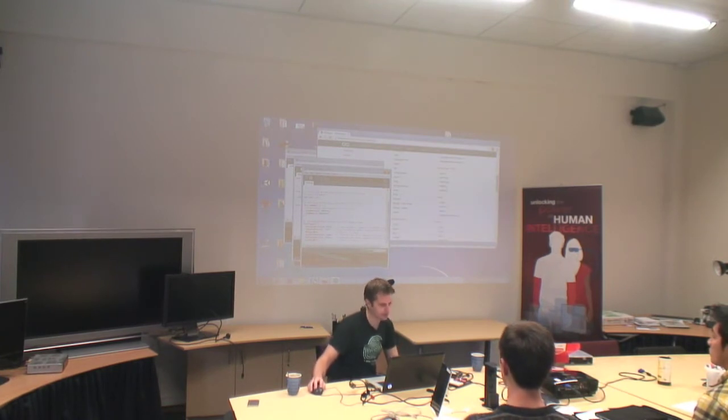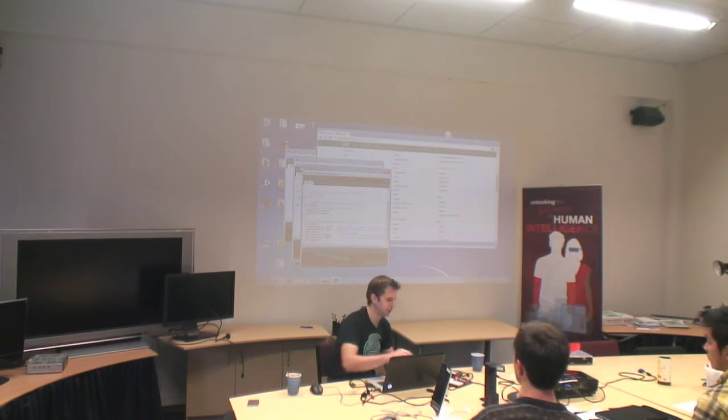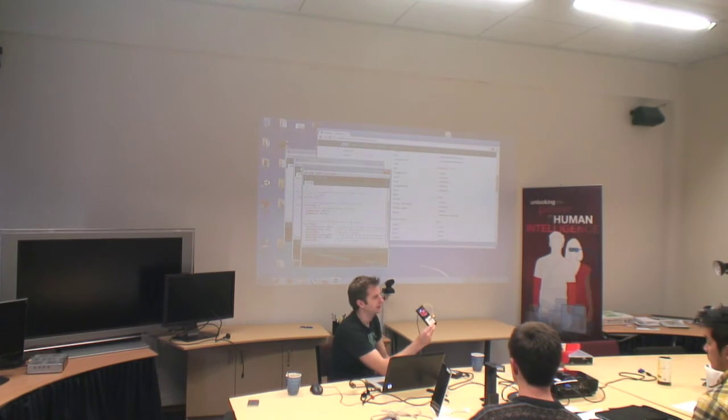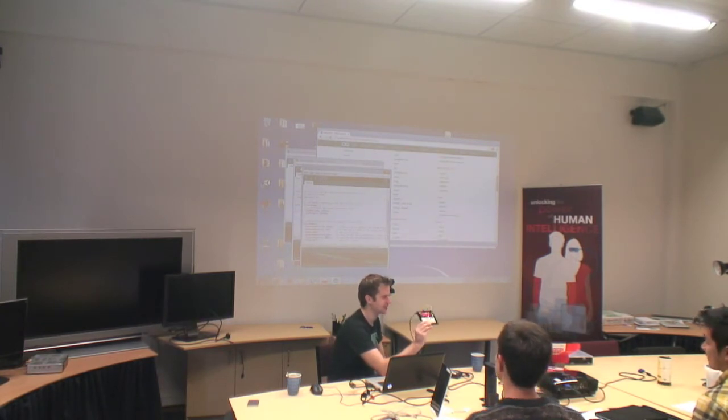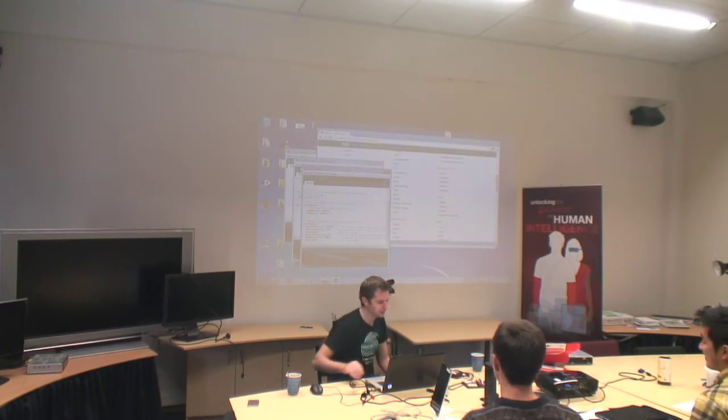Right, so now I've basically set pin 13 and pin 12 to be output, and I've said, okay, when pin 13 is high, pin 12 should be low, and vice versa. So now I have flashing yellow and red lights like a train crossing or something. It's not particularly exciting again, but before Arduinos, this was actually quite hard to do. I remember doing stuff like this in high school with flip-flops and 555 timers, and it would take a lot longer than that.